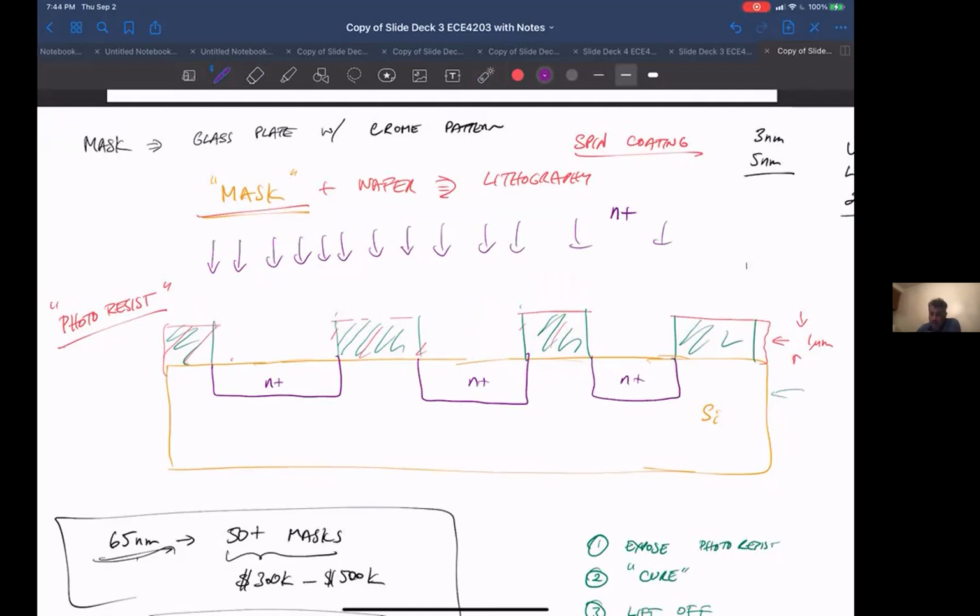Although the whole wafer is getting implanted, the hardened photoresist material is creating this pattern of N+ only where there is no photoresist. So for the sake of discussion, let's say these were my N wells, where my PMOS transistors were going to go. So the way I define those N wells is, put this photoresist on, implant it, and now I've got N+ where I want it, my wells where I want it.